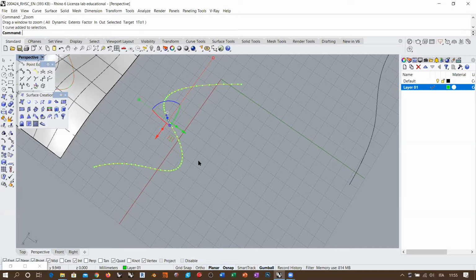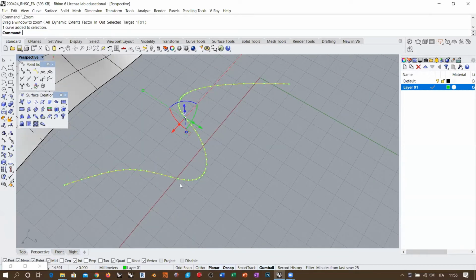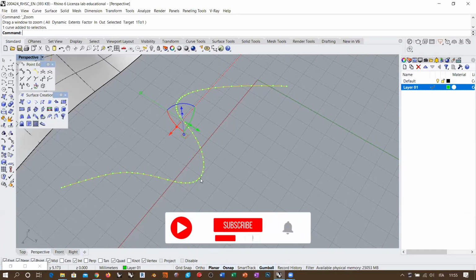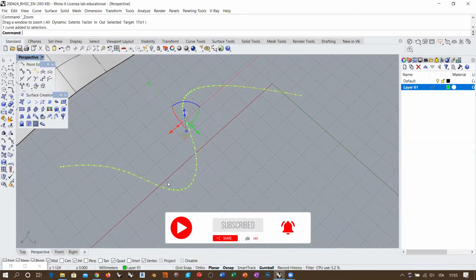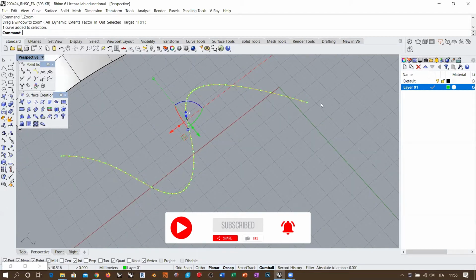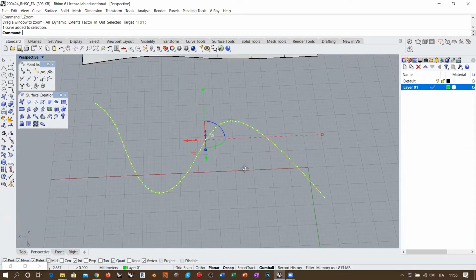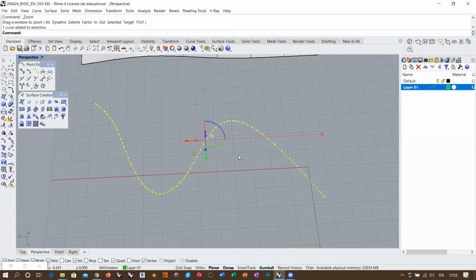Now, fitting tolerance means that the maximum deviation must be contained inside 0.001 units. And we saw this previously with Grasshopper. I showed that when the curve has more curvature, in order to maintain that tolerance, you need more control points. When the curve becomes smoother, you need fewer control points. So there is not an even distribution of control points along the path. You see that in this part, they are denser than in this area here. Okay, but this is the best topology in order to maintain that tolerance.